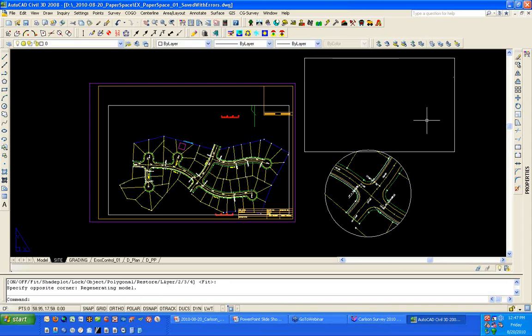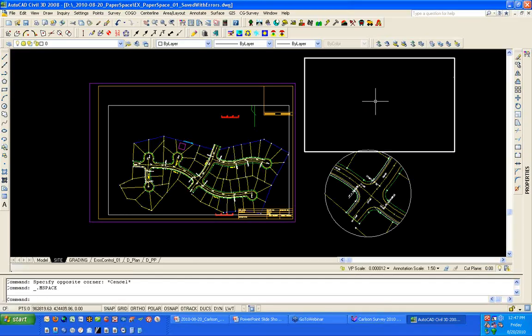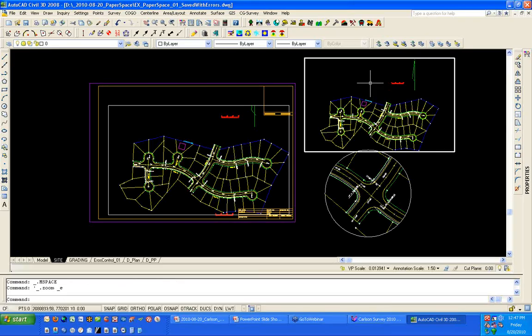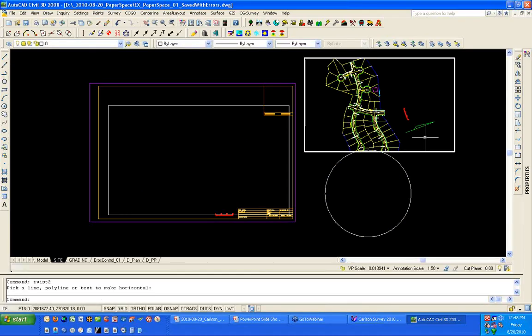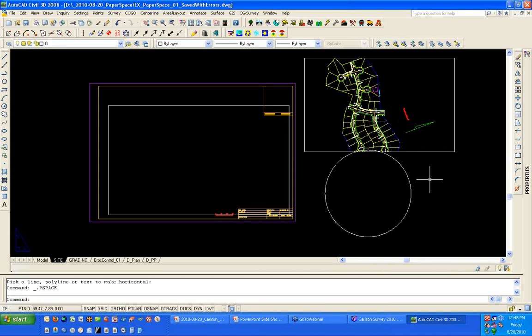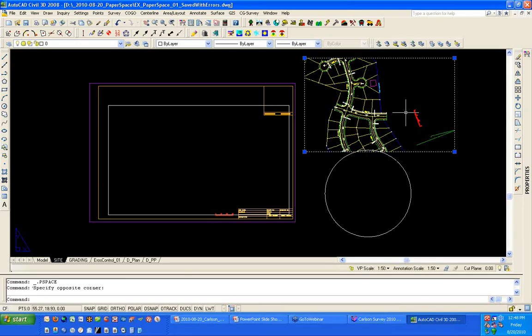And actually, I had noticed this before. When I create a new viewport with the model space twisted, that didn't work. Why didn't that work? Let me try my twist screen from here. It should have worked, though. There we go. All right. Oh, I think I know what's going on. But anyway, so I've now twisted it in this viewport. And what I would like to do, I'll lock that viewport. I'll set it to scale first, and then I'll lock that viewport.